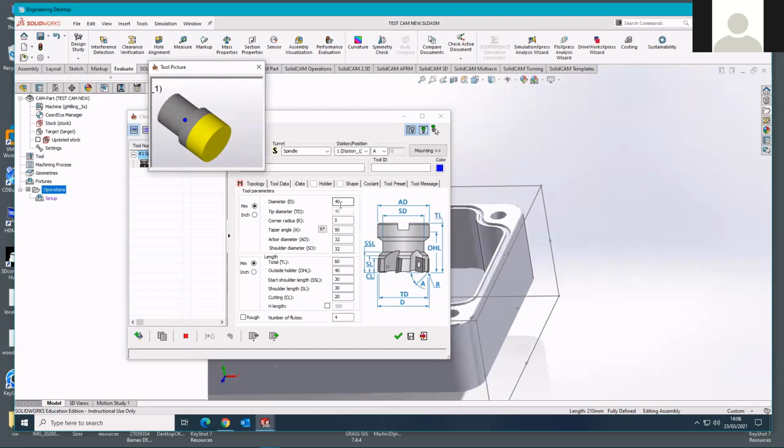So we're going to modify this slightly. We're going to use a tool which is 80 millimeters diameter. The intention here is that this tool will be of a type that uses small inserts to do the actual cutting. So you can see the graphic down here, which is a generic face mill in graphical form, has these little diamond-shaped inserts that are held within a body.